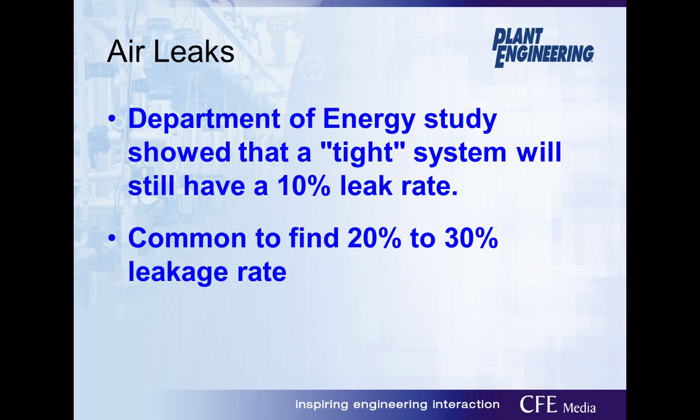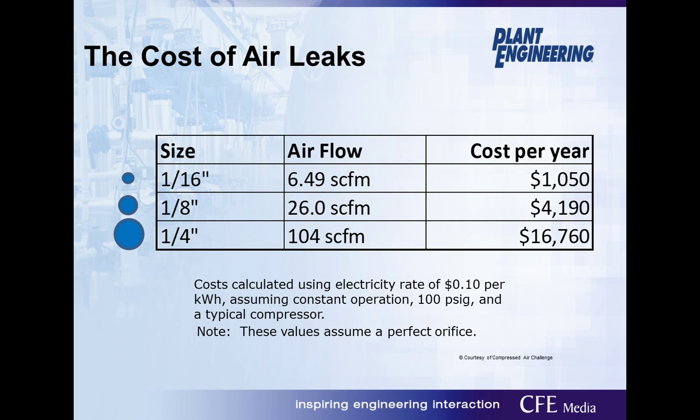The Department of Energy says even if you have a tight system, you'll still have leaks, around a 10% leak rate. I like saying it's like my house. I fix one thing here and another thing over there breaks. Same with a compressed air system. As you fix leaks, other leaks will appear, and the real key is to have an ongoing program to take care of it. Again, it's not uncommon to find 20 to 30% leak rates, and it's very costly.